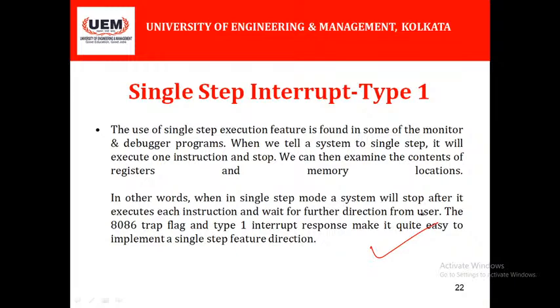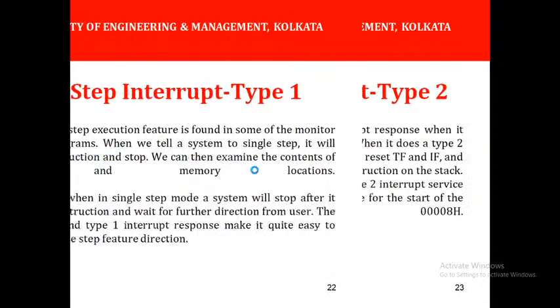So what is the use of the single step execution? The single step execution feature is found in some monitor debugger programs. When we tell a system to single step, this is an important point, it will execute one instruction and then it will automatically stop. It will not go on to the next instruction to be executed, and it will not automatically increment the value of the instruction pointer.